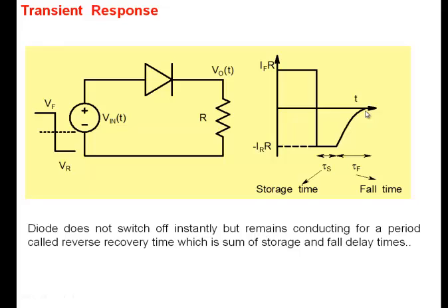The diode can conduct in the reverse direction, but momentarily. And for how much time? For a time that you see here, which is related to my transit time of the diode. So of that order of magnitude. If my transit time is, let's say, 1 nanosecond, my diode is going to be conducting for a few nanoseconds. If my transit time is milliseconds, my diode is going to be conducting for milliseconds. So it's all related to the transit time of the diode here. So it's a very, very important parameter which tells us how long my diode will conduct in the reverse direction here.